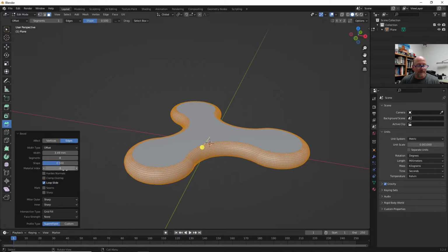And just click and make sure 3.5. And I have 8 segments. Kind of want to maybe click there and let's go 12. And what I'm looking for is the edges, the faces to be roughly pretty square, and so they look pretty square to me. And so that makes a nice round edge, as round as the curvature and so forth.